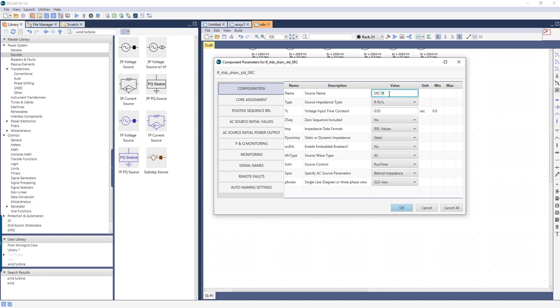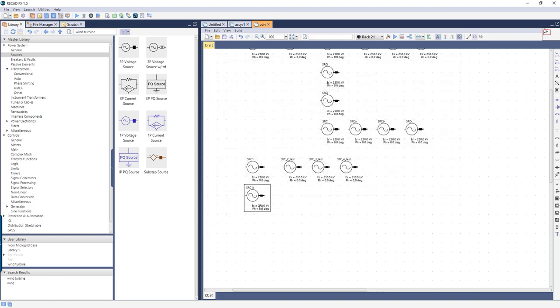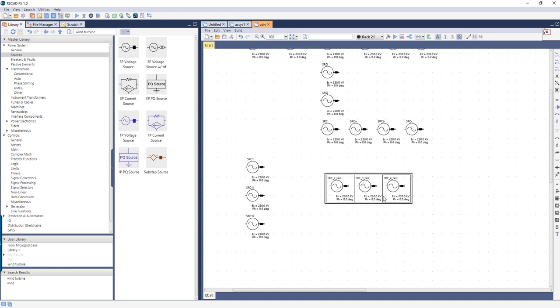Flattening can be helpful when we copy and paste a group of components. So auto naming works on a per component basis, which means if I just copy and paste a group of components with incrementation on, like I'm doing here, I can end up with some duplicated component names because auto naming is incrementing the names for each component.